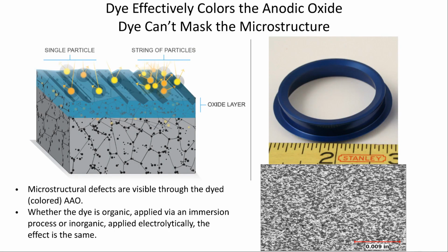So look at this microstructure on the bottom right. This is also 7075 T6 material. In fact, this is also part of the same aftermarket bicycle headset. The complaint was, this is too dark. Why doesn't it match? And here's Bob. Bob's nothing more than a shadow. Well, we developed the microstructure through anodizing, and that clear lens is looking directly at that surface. There is no level of recrystallization. In fact, it's been hampered by the structure and constituents of the metal itself and how it was heat treated. We see evidence of dynamic recrystallization in the structure. We see a lot of things that keep this dark.